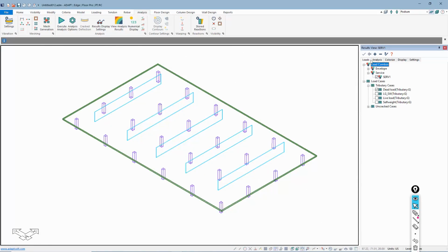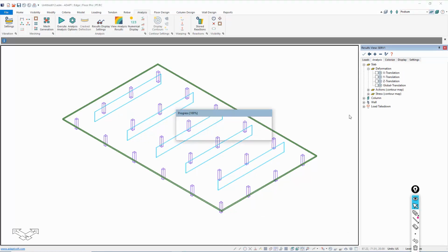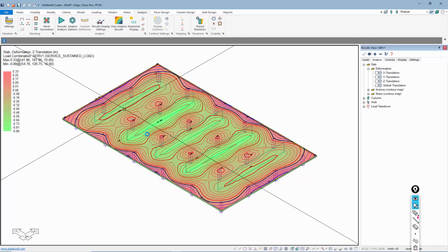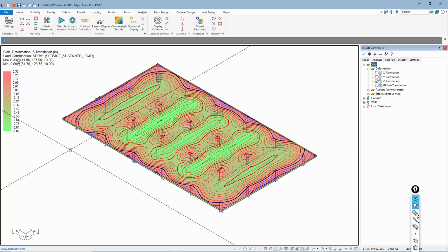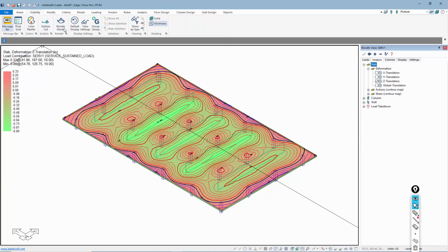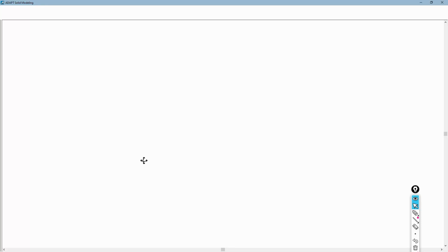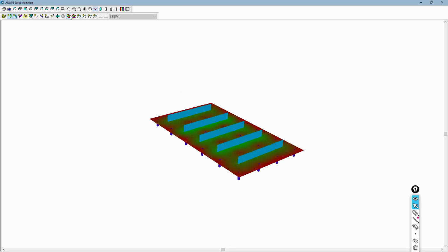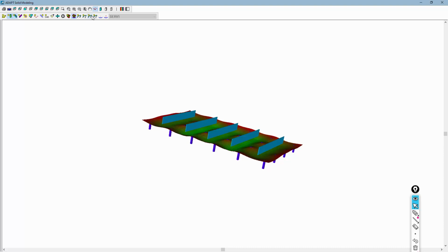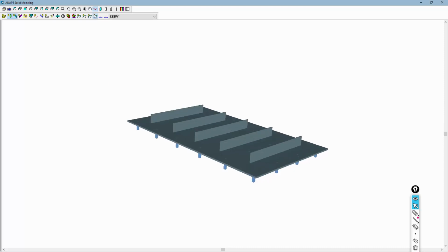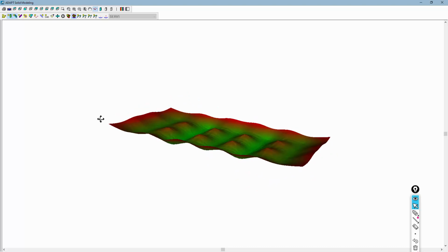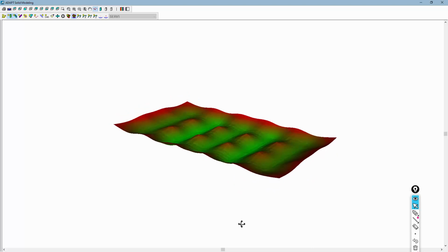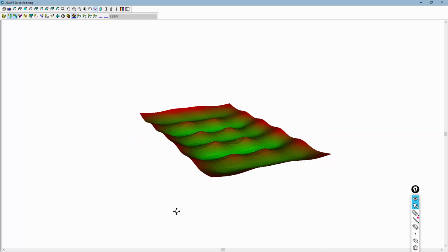And we can take a look, for example, now at the slab deformation just to see what that looks like at these locations. So you can see some hot spots there where we have max deformation for that particular load. I can always go over to render model, and under the render model we get those hot spots shown, get some warping there. I can look at more of a realistic view of what that actually looks like under this view. You might have to warp that. So this might be a better warping tool here, but you can clearly see the bearing wall stack and the loads that are coming down on those locations from the load takedown.